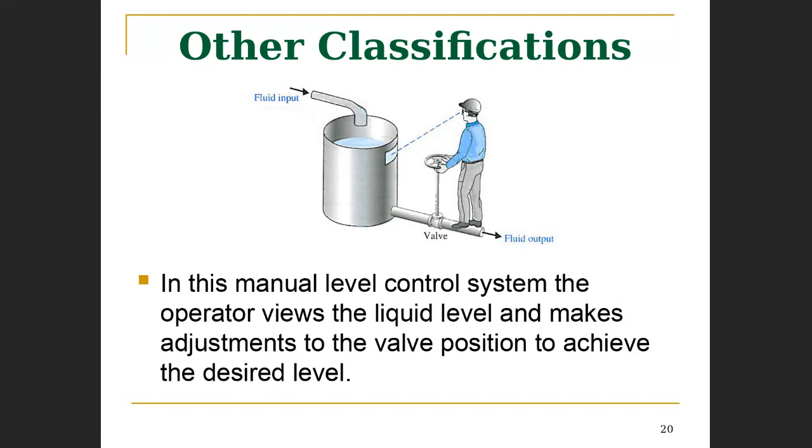So you may find that some material might say, in the absence of electronic feedback, the system is open loop. But here I'm laying a foundation to say, in my definition, once you have measurement, it doesn't have to be electronic. Once you have measurement of the variable you're seeking to control, then it's a closed loop system.